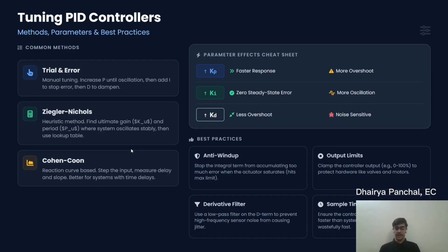But with respect to robotics, now as I'm coordinating the self-balancing robot, I will give you an analogy with the self-balancing robot. તો જ્યારે આપણે રોબોટને બેલેન્સ કરાવવાનું છે, initially what's the trick that we use to tune the PID controller is initially you put a very high proportionality constant, right? તમે proportional constant ને એક particular value આપી દો, let's say 50. Then you run your robot. તો એ રોબોટ તમારું આમ oscillate કરતો રહેશે. Your robot will just continuously vibrate at one place, right?